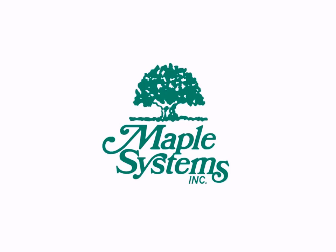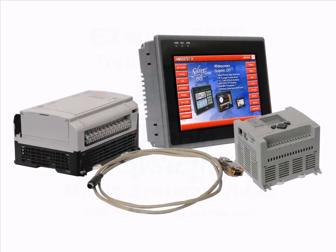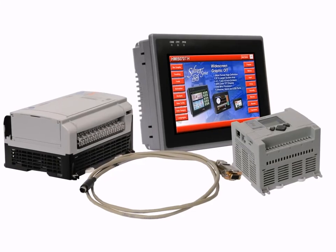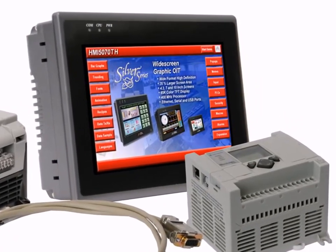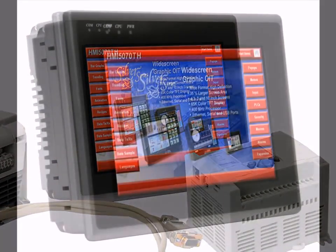In this video, I will explain how to set up your HMI to communicate with your PLC or controller and demonstrate creating a simple test project to verify communication. Before beginning the process of configuring the HMI, gather all the necessary information and documentation. The first thing you will need to know is the model of HMI and PLC you are using, how you intend to connect them, and what protocol you will be using.